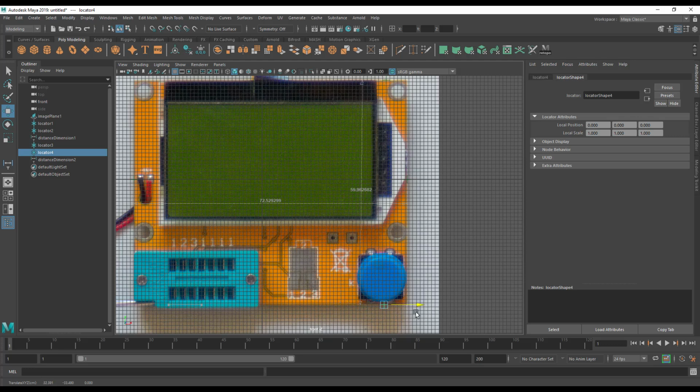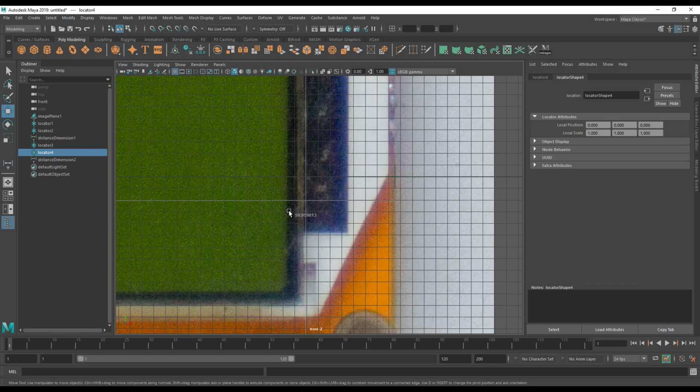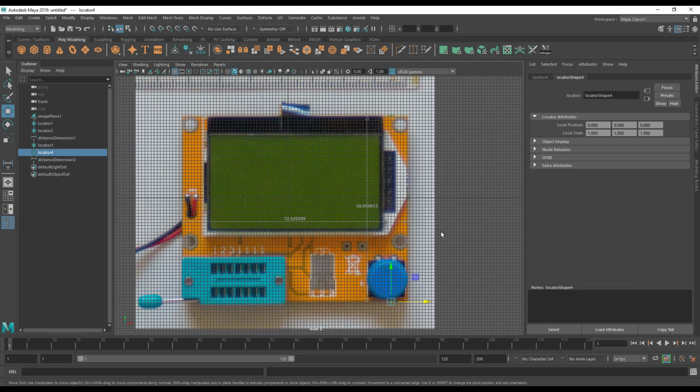The cosine error is going to come and bite you, and we don't want that. So let's just make sure this is as straight as possible. And to be honest, this is well within the bounds of tolerance for 3D printing, so it's good enough for me. Now the other thing we want to do is make sure that our piece here is central to the